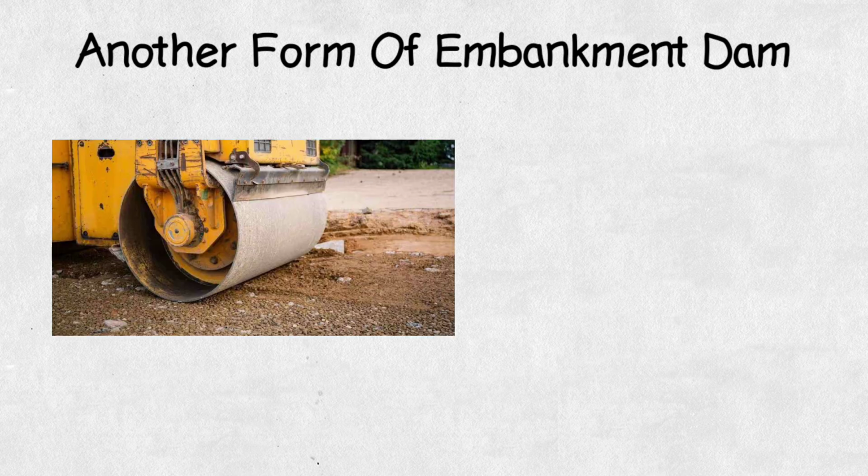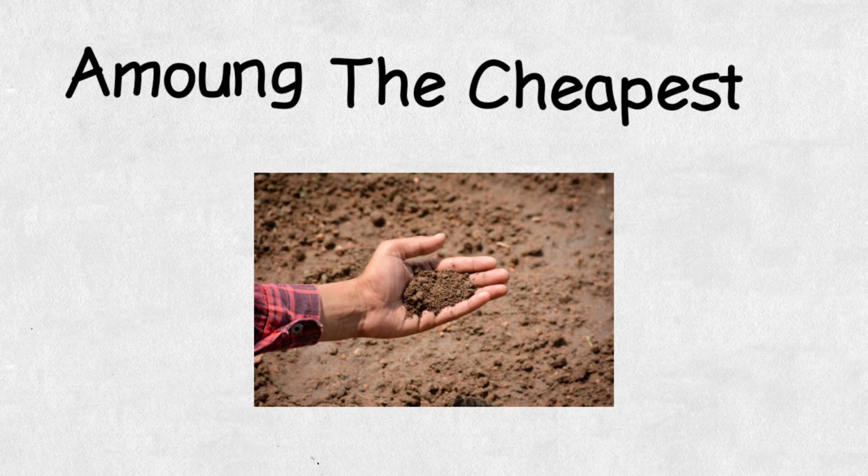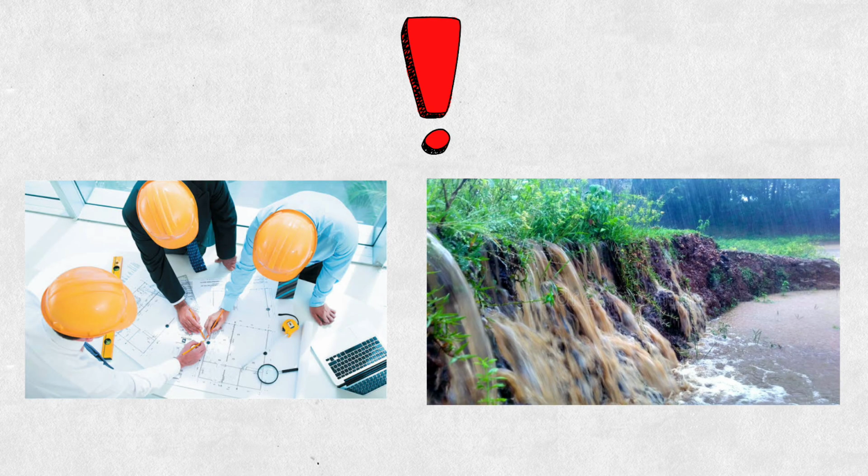Earthfill Dam. Another form of embankment dam, but built almost entirely from compacted soil rather than rock. These are among the cheapest dams to construct when suitable soil is available nearby. However, they require careful engineering to prevent water from seeping through or eroding the base.